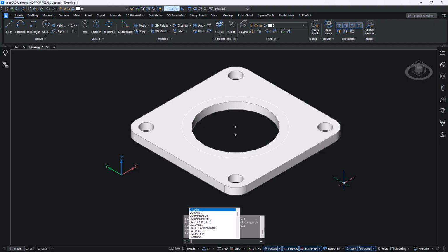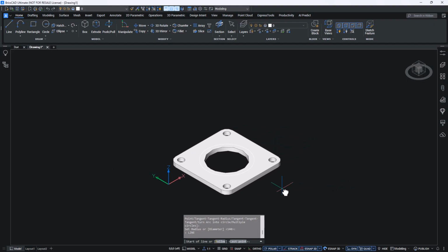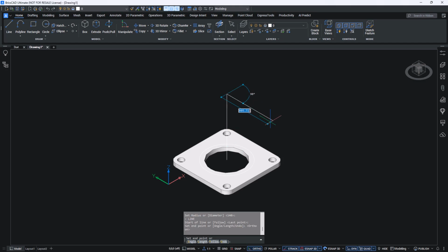To create the path we'll use the line command. The first line has a 500 units length and is parallel to the z-axis. Enable the orthogonal mode from the status bar, and move the mouse upwards. Next, continue drawing a line of 500 units parallel to the y-axis. Next, use the fillet command on the two lines with a radius of 250 units.